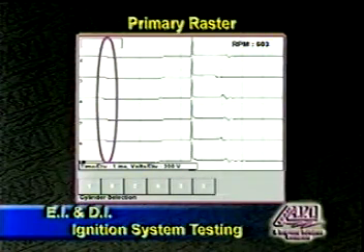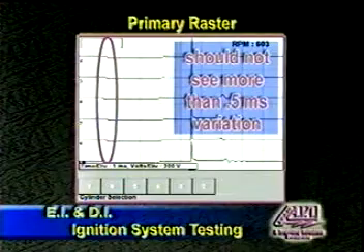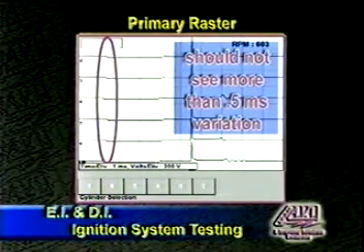When you're looking at the alignment, if you see more than 1/2 of 1 millisecond variance, that would be indicative of too much mechanical wear in the distributor shaft, too much wear on the distributor drive gear, a sloppy timing chain, a magnetized distributor shaft, magnetized shutter blades on Ford's TFI4 systems, or upper distributor shaft bushings like on the Honda systems.